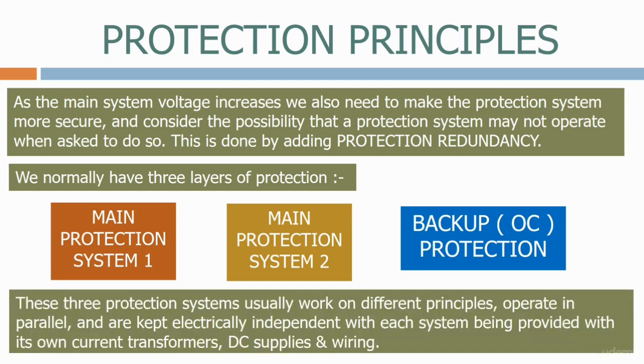These 3 protection systems usually work on different principles, operate in parallel, and are kept electrically independent, with each system being provided with its own current transformers, DC supplies, and wiring.